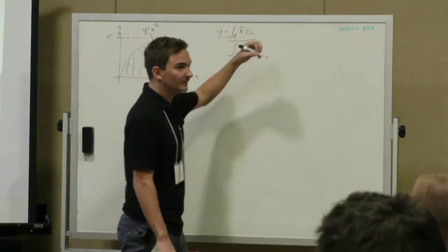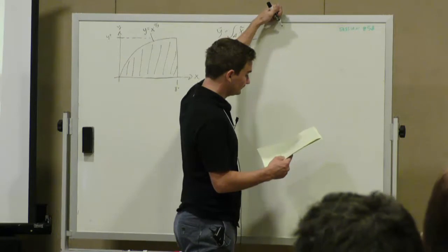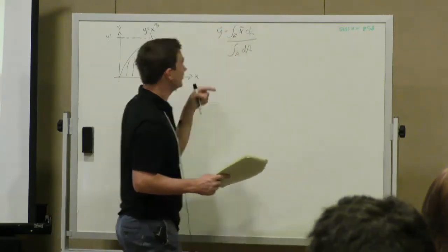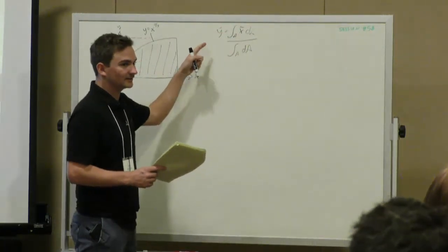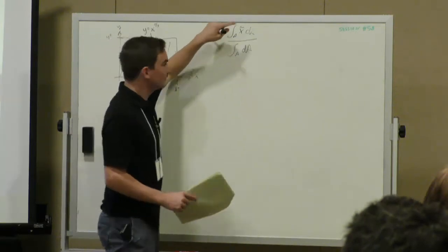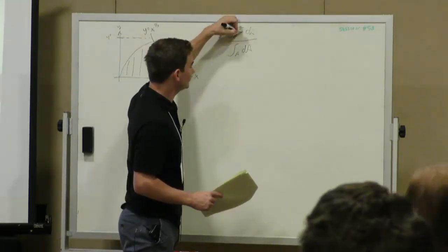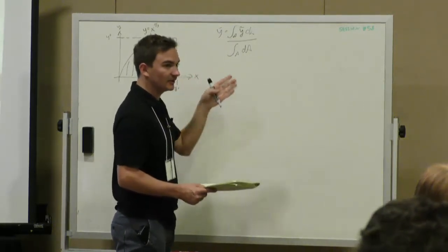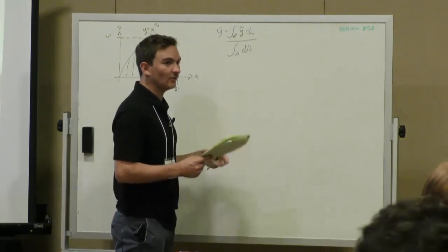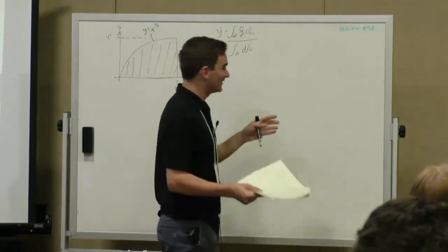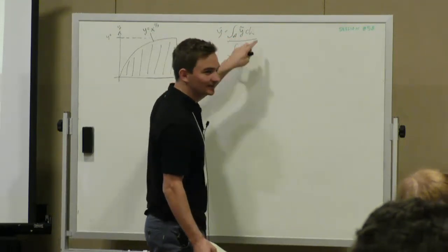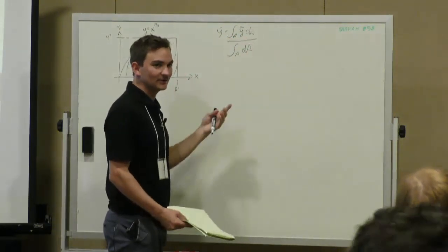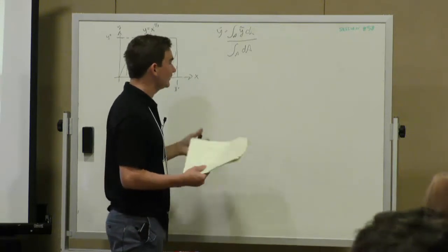So similarly, when we did our composites, but is this for the y bar? Is this x tilde? Yeah. So the original one was correct. It is y tilde. However, for centroids, that's when we use y tilde. So centroids, we still use y tildes, but for moment of inertias, you use the opposite. And those would be squared.